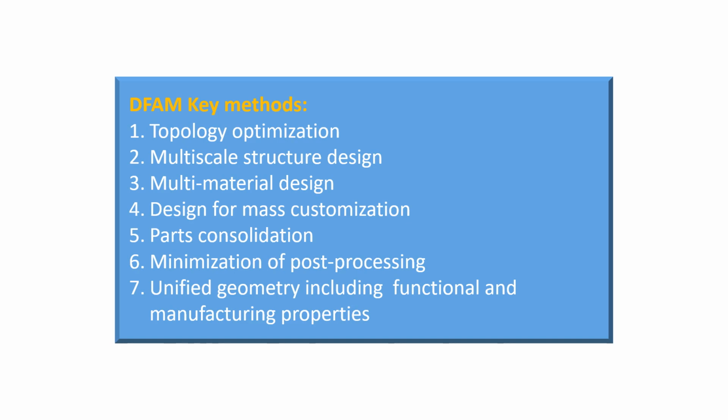3. Multi-material structure. In some of the methods of additive manufacturing, several materials can be used in printing, in which case the special desired properties are obtained locally in the part. In metal printing, this is possible, for example, via directed energy deposition methods.